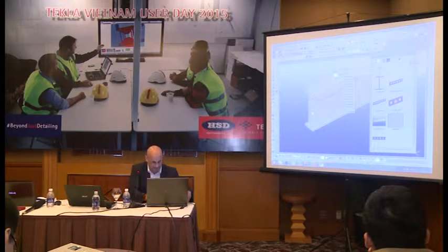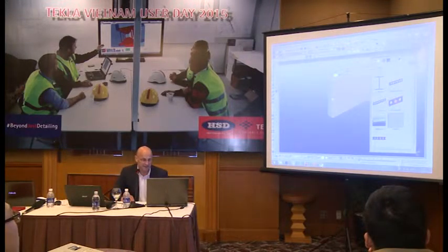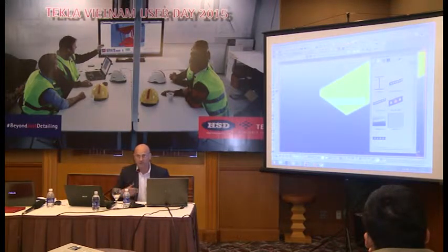PL, let's say 300 by 50. So now it's a plate. So it's much easier to set these up and say, look, that plate, I want it to be about this edge, the edge, the centre, or the side, like so, and it's at that rotation. So it's a much easier way of working.